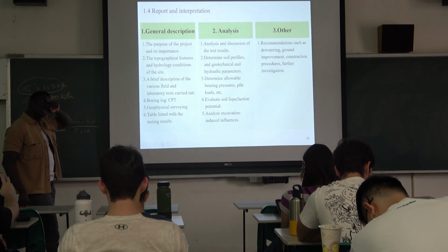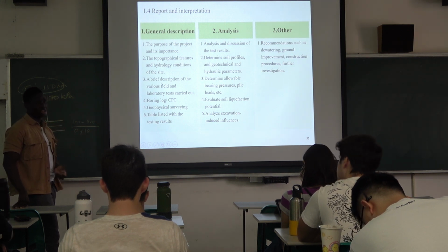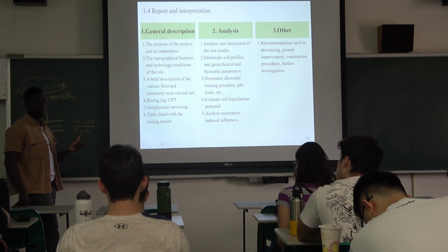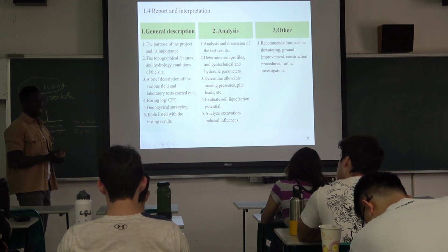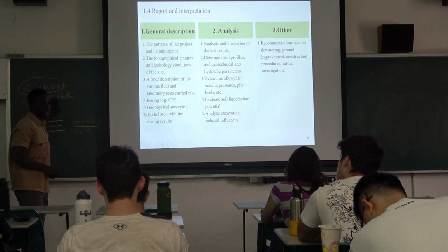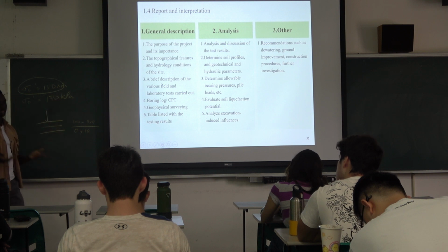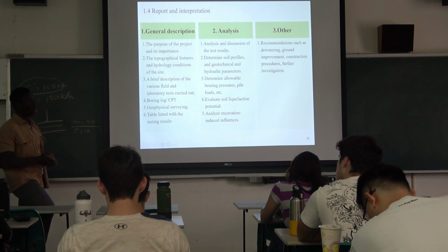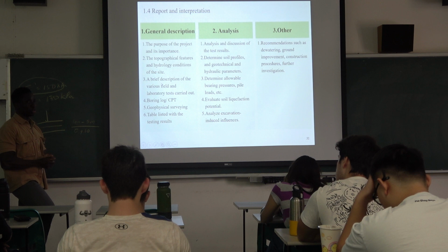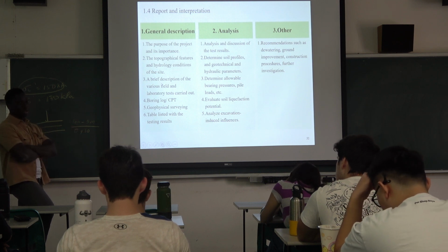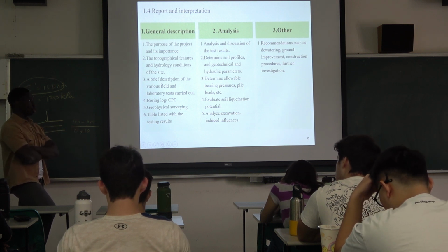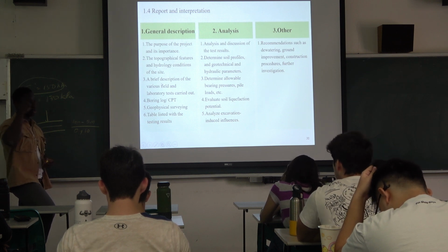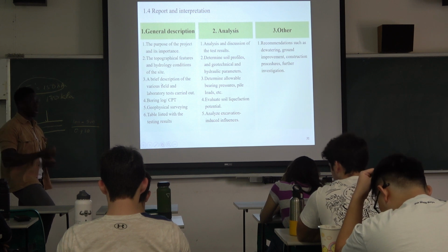Soil liquefaction typically happens mostly in sandy soils. During an earthquake, when the ground is shaking, the soil, instead of behaving like a solid material that is strong, behaves like water. It's just like water. It has no resistance, it has no force. So most of the structures underneath will probably fail in that type of situation. So you need to evaluate the soil liquefaction potential so that you can take that into consideration when you are building the structure.